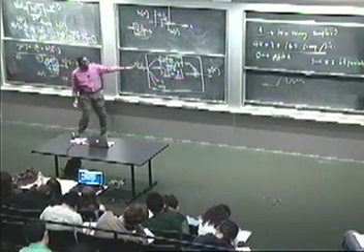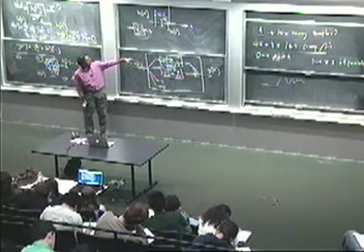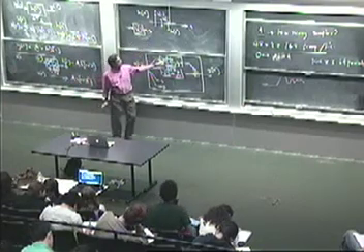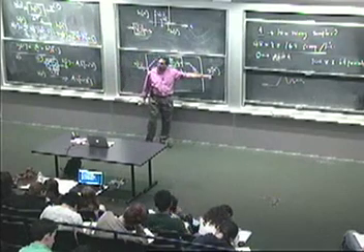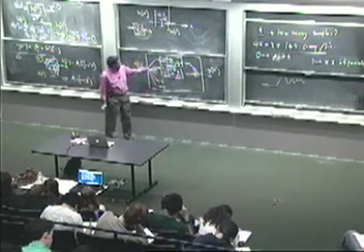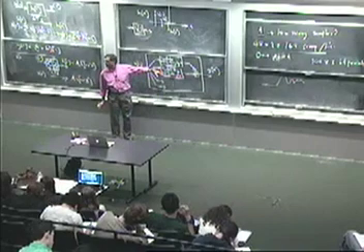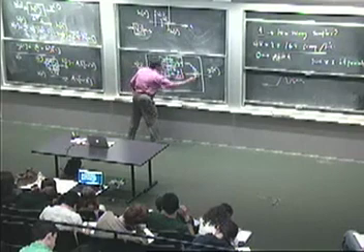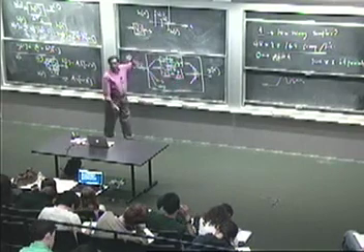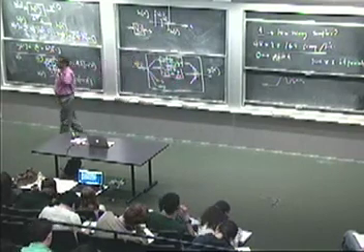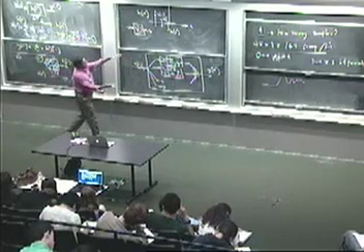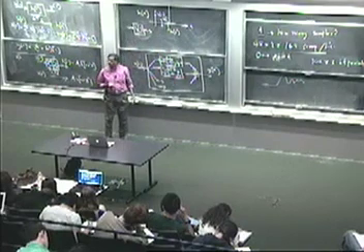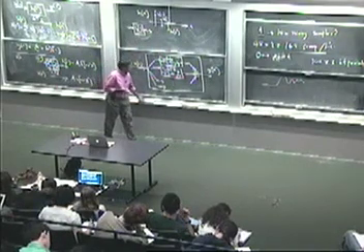If I put a unit sample in here, what comes out? It's going to be exactly that, right? Because the unit sample would get scaled by h0, delayed by nothing, will come out there. The unit sample will get through this path, scaled by h1, delayed by 1, come out there. When you assemble all of these with this summer here, you're going to get exactly that response. So here's another way to think about what's sitting inside an LTI system whose unit sample response is given to be that. Okay?